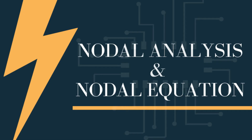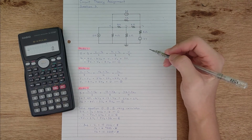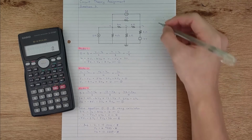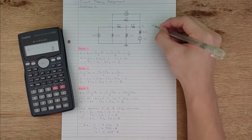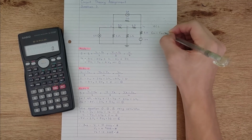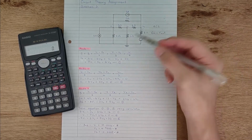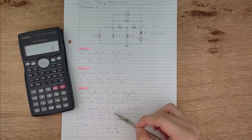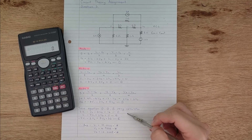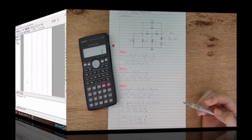In this video, I'll talk about nodal analysis and how to write nodal equations. So let's get started. We are asked to solve this circuit by using nodal analysis. To form nodal equations, we have to use Kirchhoff's current law, KCL, which is current in equals current out. Since this circuit has 3 main nodes, we have to form 3 nodal equations, then solve them simultaneously using a calculator. To prove my answer, I'll be using Multisim simulation.